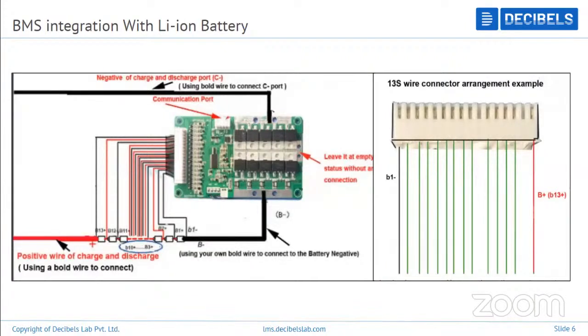Just make sure that you don't blindly use thick wires, because if the length of the wire is more, the current will be wasted there, or you won't be able to use the load properly based on the application, because it's a wastage of current directly from the battery pack. So always go by the gauge calculation according to the current flow.